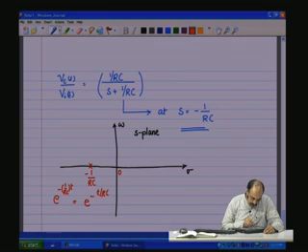If this pole starts coming closer to 0, then what is happening to R C? R C is becoming higher and higher, till when it becomes close to infinity, this 1 by R C is at 0. So, as the pole comes to 0, the decaying action becomes slower and slower, because the R C time constant becomes larger and larger, until at this point there is no decay, which is integral action.